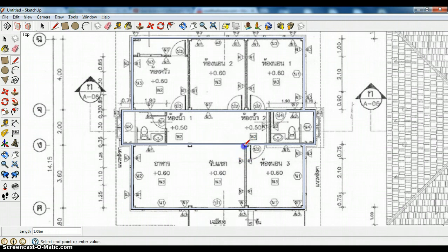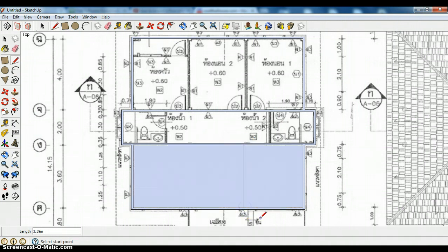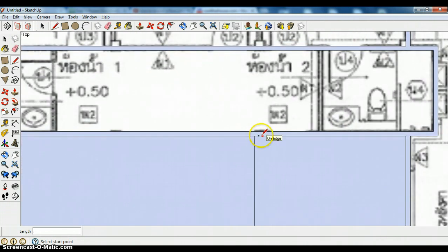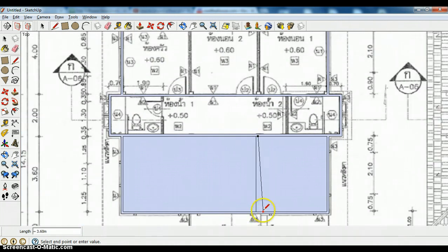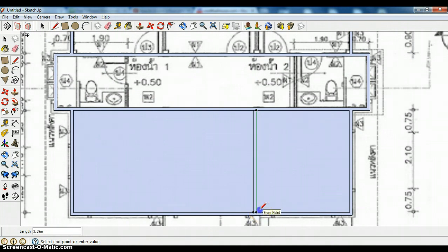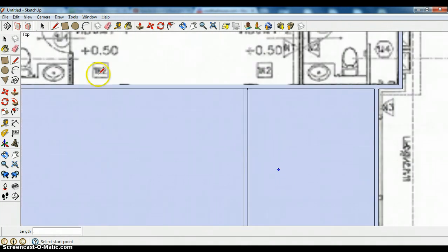So anyway, we do a line here. Take a tape measure. Click and move it, but don't click again to finish the move. And type 0.1, enter. That gave me a little mark where I want my other pencil mark to go. Oops, escape. It's best to zoom in so you can pick up your mark right there, and then just zoom out to finish the move. Right there.